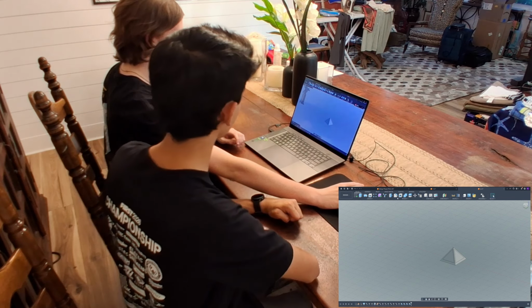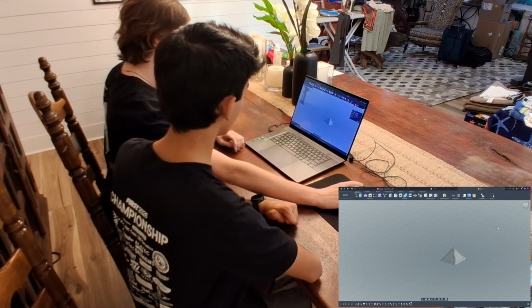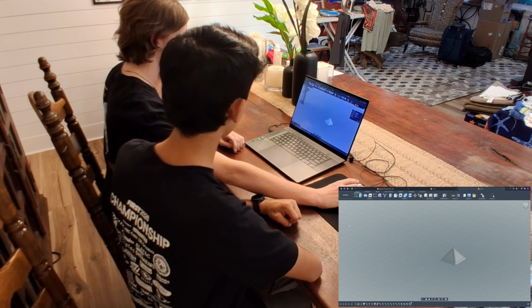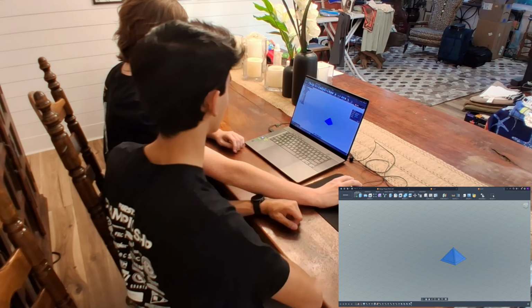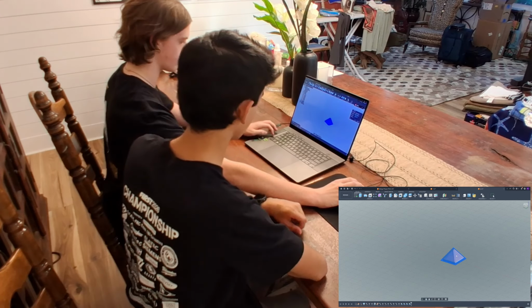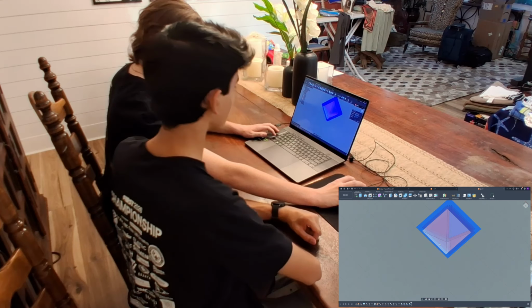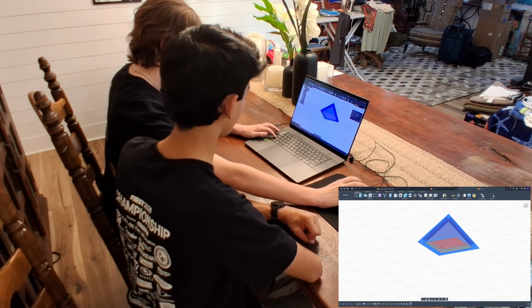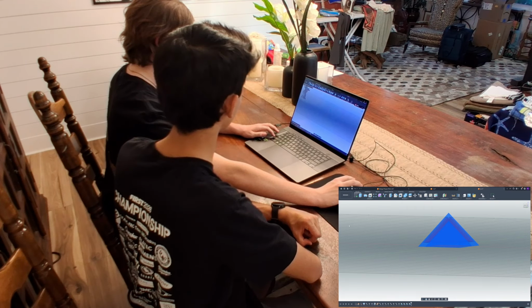So modify. You go to merge or combine, yeah, combine. Then select your target, which is the big pyramid. You already have it shown. Then make sure you hide that so you can see all the small ones. So select all your small pyramids. Make sure you get the bottom one too. Nice. And then just click OK. And then you want to show that body again.